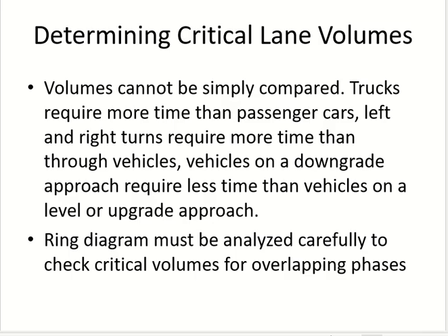The next thing we do is find out the critical lanes. You have the phasing plan; you look at which lanes go in each phase, look at their volumes, and find out which one is the critical volume. We discussed critical volumes earlier as well. If we have 2 lanes, how do we decide which volume is critical? The one which needs more time. The more time can depend upon the type of movement as well as the number of lanes, and it can also depend upon the gradient, if the gradients are different on the approaches.